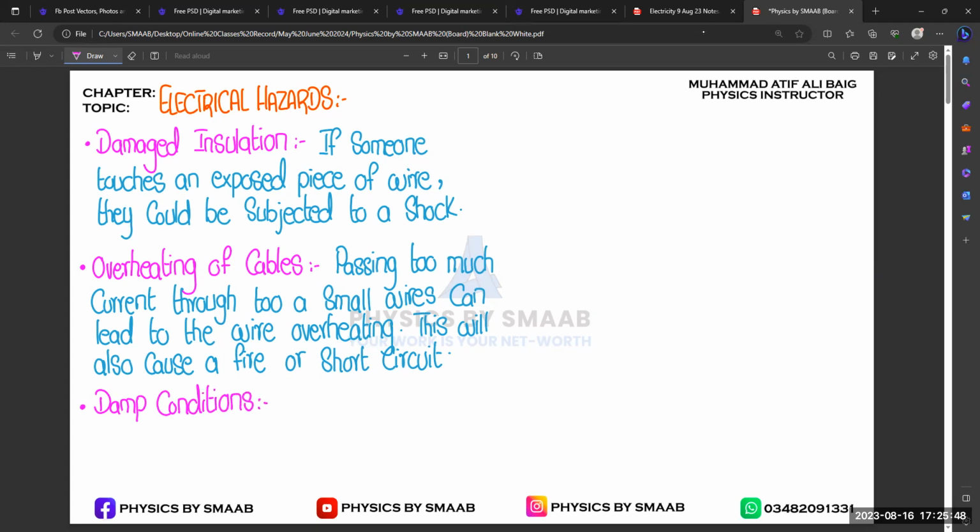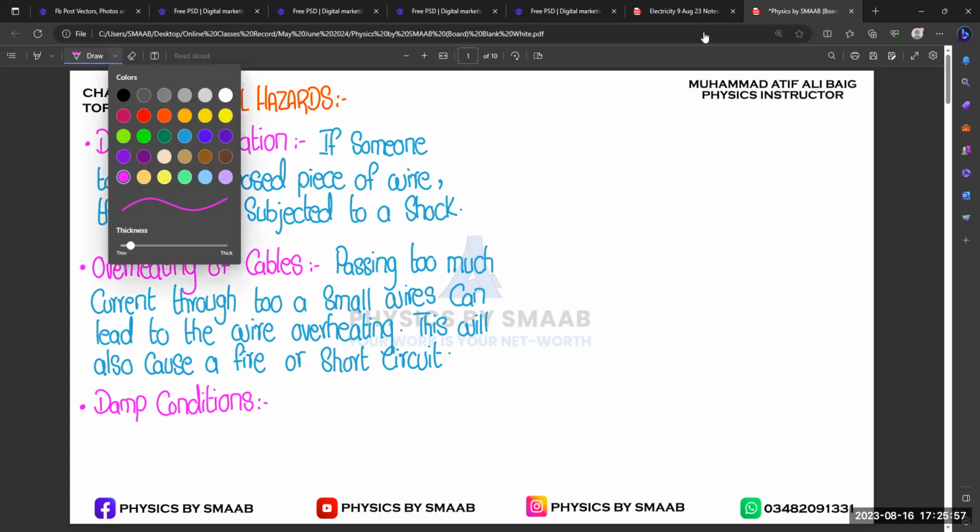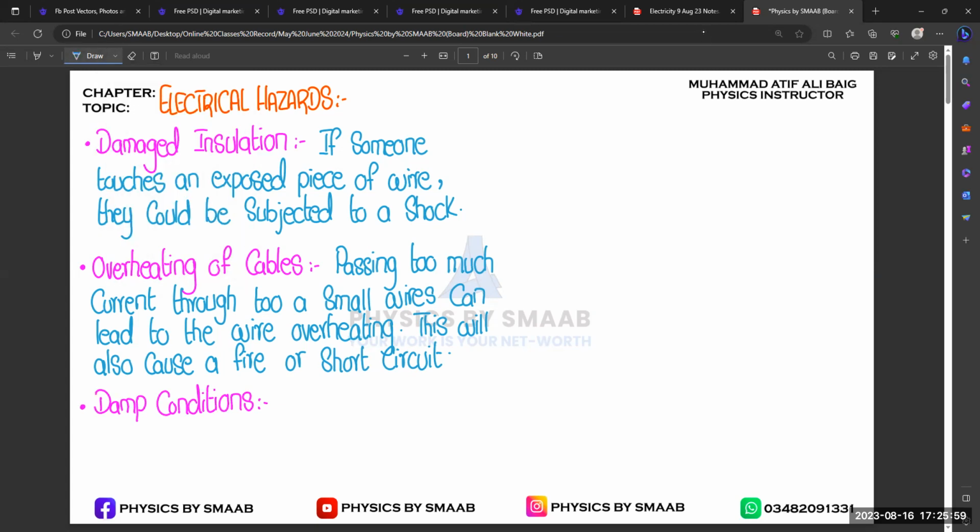Damp condition means in the rainy season, or let's suppose humidity is very high, so wires and all things are slightly wet, and we should not touch any wire without wearing shoes or slippers or having a rubber sole. That can also cause electric shock through the human body.